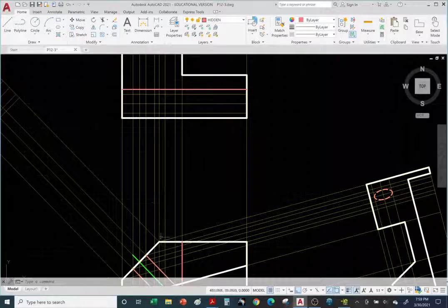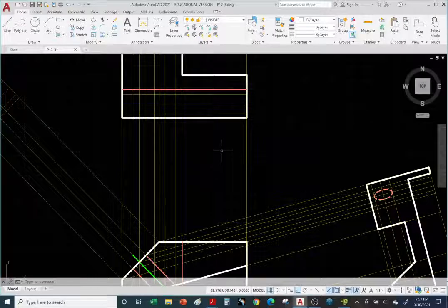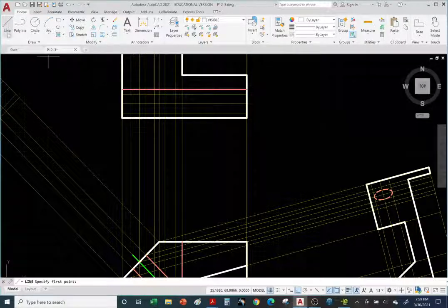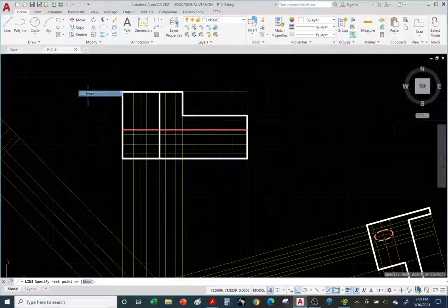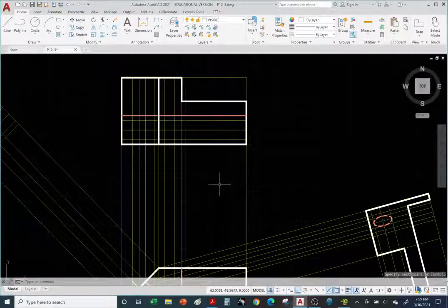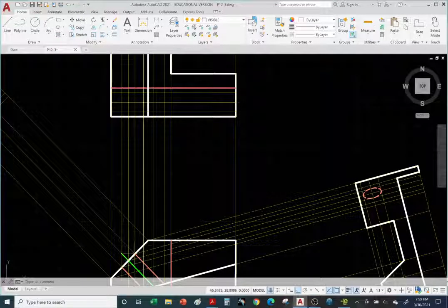Now we have an object line from this vertex. Line command, visible object layer, from this vertex go straight up. Click. And there it is, right click, enter. So it looks like we have everything in the top view except the hole. This one's a little bit tricky.